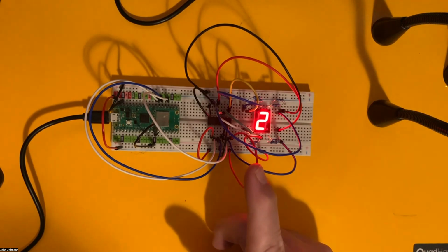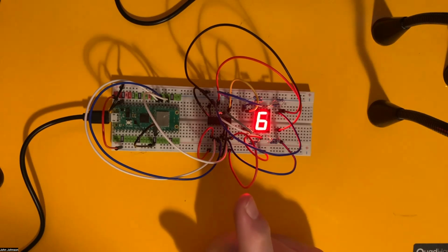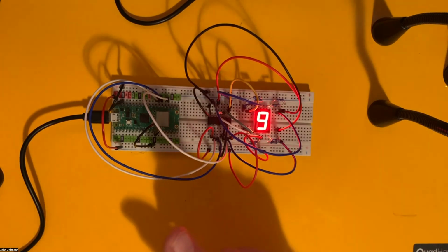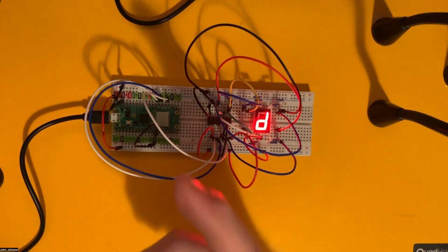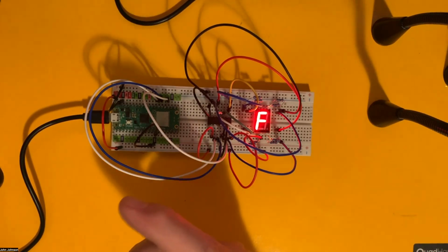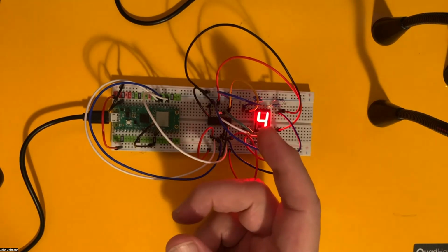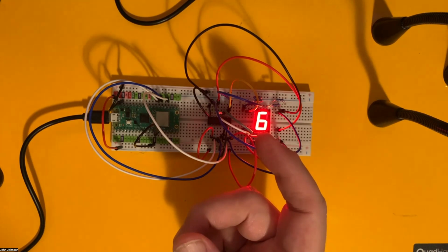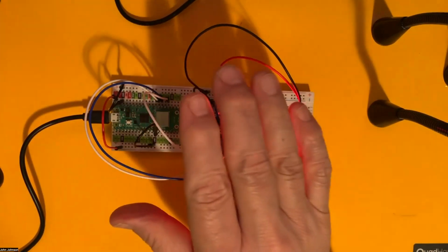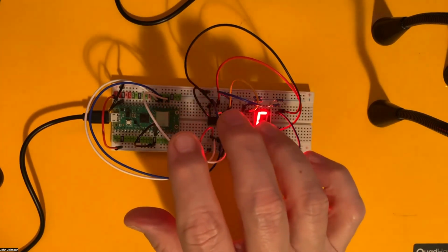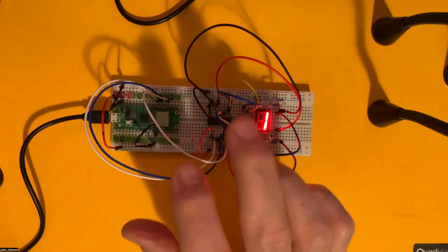To be honest, I did about an hour-long video last night of this same one, and I was having trouble. The trouble was that one of the legs of my IC chip bent under it, and I had no idea. It was acting erratically. I would get this thing to print sometimes, but not all the time. If I just pushed my wires, I would get different things coming up. They were messed up, but there were things coming up. I was like, what's going on here?